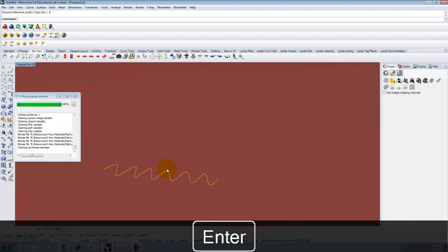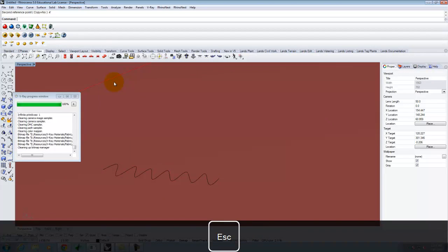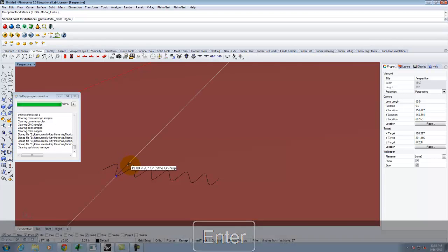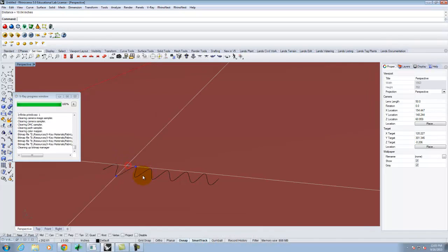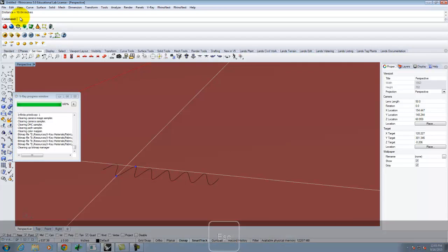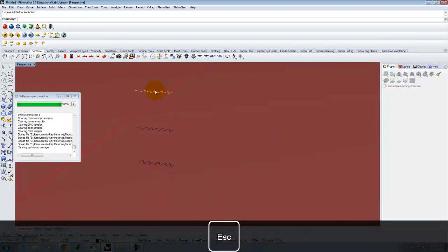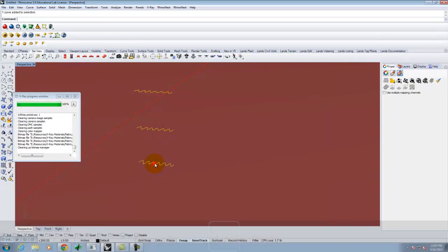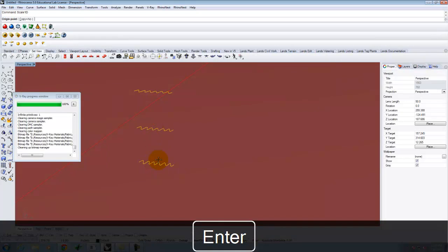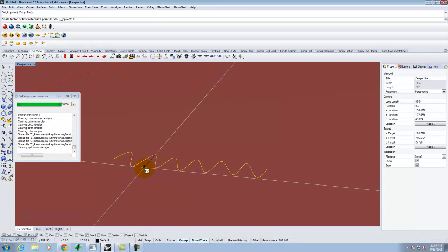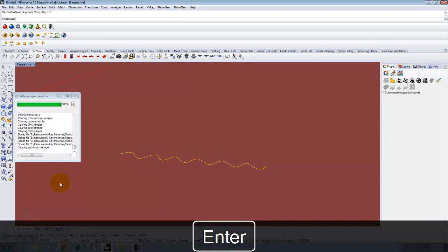Okay. The other thing that I probably should measure is the distance between these two. So that's a 10-inch fold. That's a pretty thick set of folds. So let's scale that down too. Let me take this, this, and this. Scale 1D. I'm going to go from here. That was my 10-inch. We'll go to maybe a 4-inch fold, something like that.